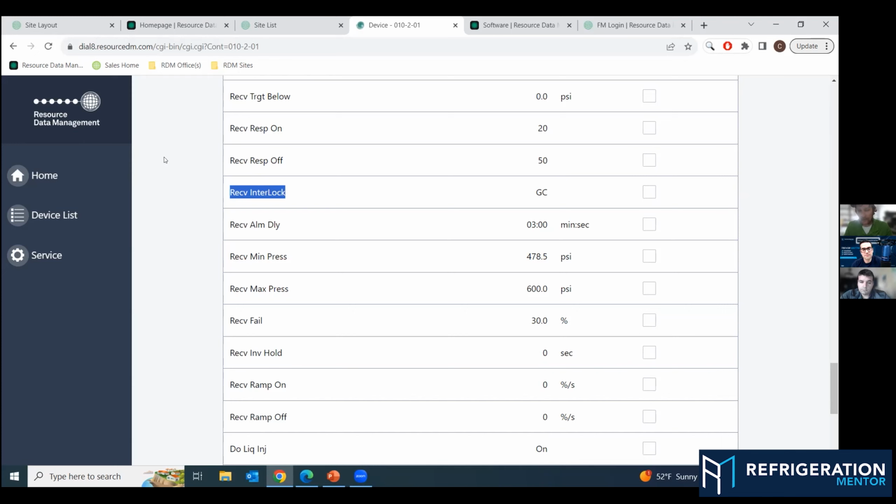The only thing that I see that on the recent update got taken out is there used to be a gas gradient, and you could set up the gas gradient for the certain CO2 we're using. So the UK used a certain gradient on CO2, like they were using refrigerant grade or bone dry or vice versa. Well, they have different grades of refrigerant that these techs are using. It makes a difference in the background of the software because it has different flow rates and different weights. I'm not going to get into the boring details of that, but it does make a slight difference. You used to be able to come in here and set those gas gradients for what CO2 you were using. They took that out, but it is what it is.